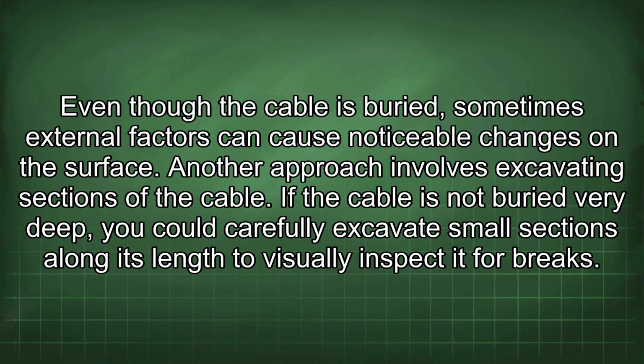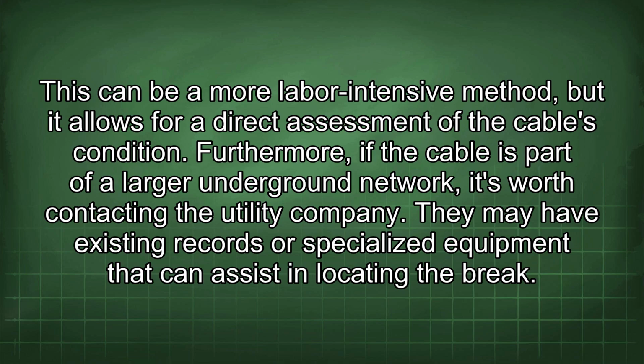Another approach involves excavating sections of the cable. If the cable is not buried very deep, you could carefully excavate small sections along its length to visually inspect it for breaks. This can be a more labor-intensive method, but it allows for a direct assessment of the cable's condition. Furthermore, if the cable is part of a larger underground network, it's worth contacting the utility company. They may have existing records or specialized equipment that can assist in locating the break.